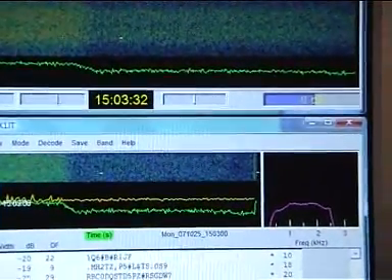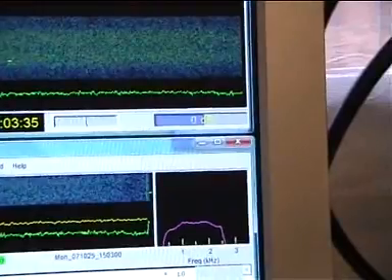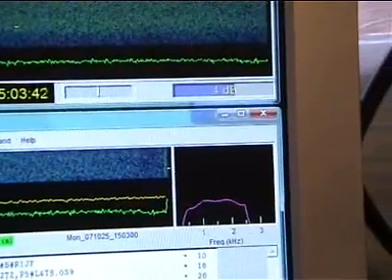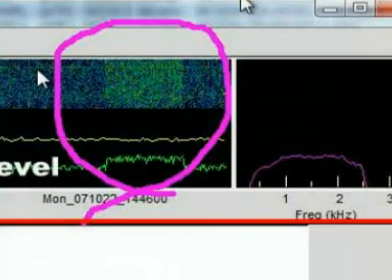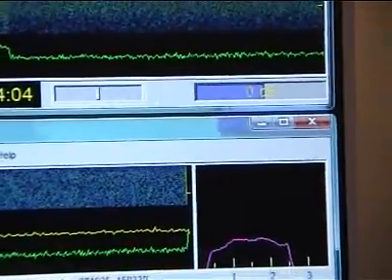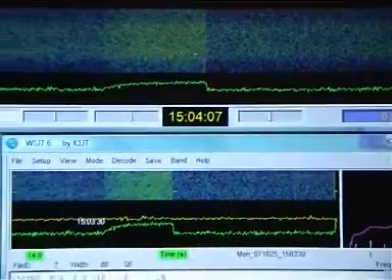Provided you do not have a particularly noisy environment in which the noise floor constantly and frequently fluctuates, hopefully WSJT will sit happily at 0 dB. It is during the school half-term, and the noise floor is fluctuating quite considerably as there is a lot of electrical activity in the vicinity to me. But as you can see here now, the level has settled at 0 dB, and this is the normal operating environment for WSJT. That concludes setting the levels for RX.